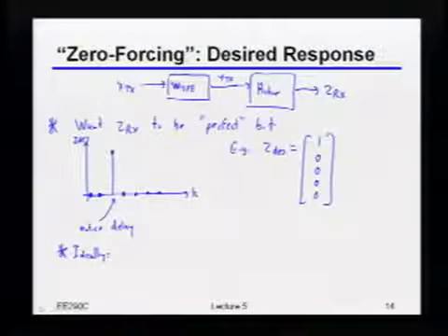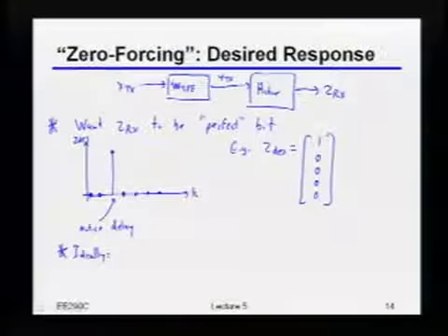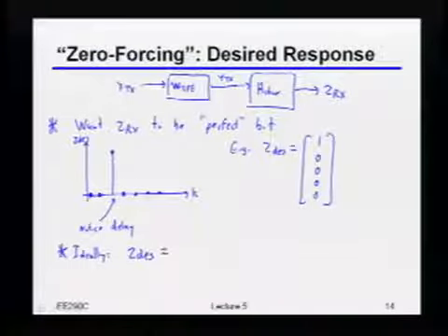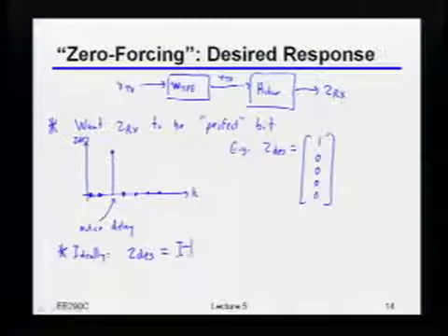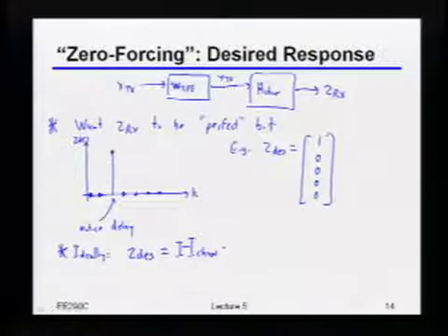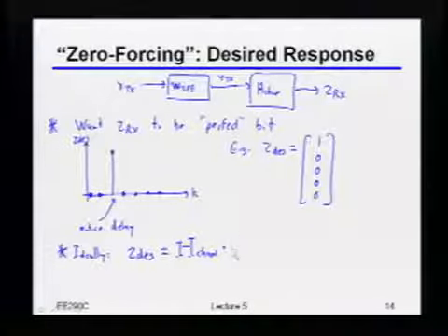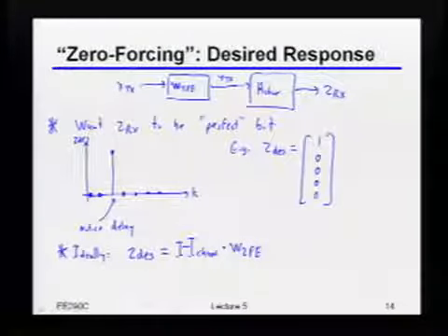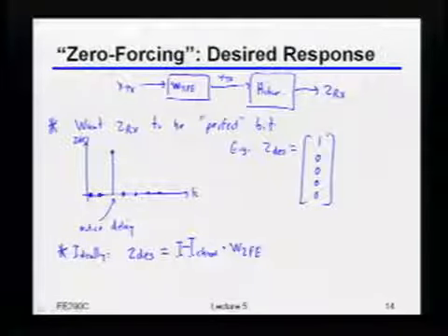So we know that by definition ZRX is equal to the channel convolved with YTX, right? But what we really ideally want is that the ideal desired received symbol, which I've called Z desired here, should be equal to, as you said, that channel applied to, let me write it this way, YTX, which remember is really just whatever my equalizer coefficients were, right?